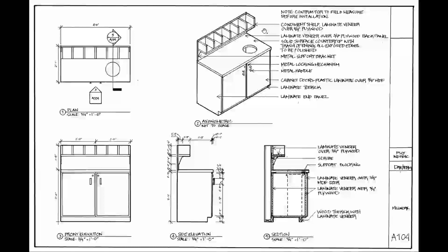So what you can see here with these leaders, and again, it's got an arrow at the end, but anytime we see information pulled out from an object, we use what they call a leader line. So you can see very consistent ending point, consistent line work on the edges of the arrows, and then it's touching right exactly on the object. It's not overlapping, it's not crisscrossing anything. It's going right up to the object.